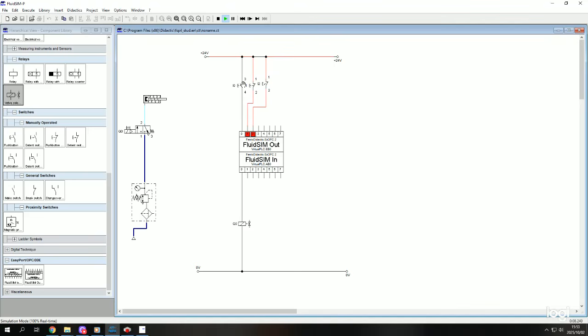So if we were to give this a scenario, we would say when you click your push button, your piston rod needs to advance. When you release your hand from the push button, it must retract automatically. Why is it retracting automatically? Because of the spring return on the acting cylinder as well as on the valve solenoid. So let us test it out. I click my push button, the piston rod advances. I release my hand, it retracts automatically. So this is exercise 1 on your lab guide.